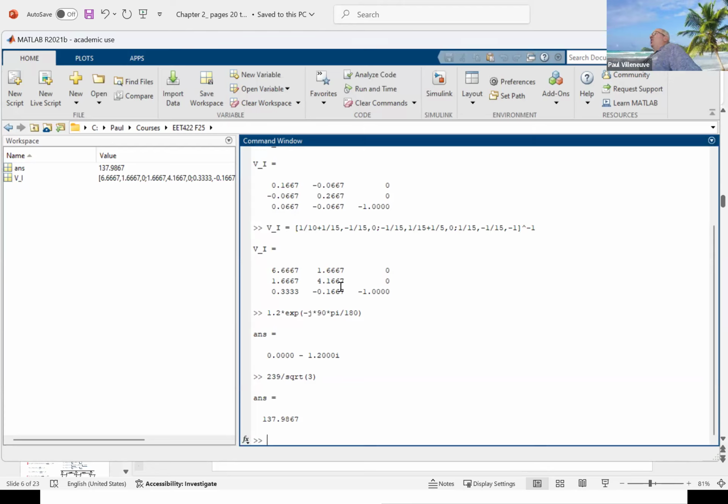Because now you're talking about a really long span. It's hard to get a tree that's going to be 100 feet tall that's perfectly straight. So when you've got to get really tall and you're running very long distances, you've got to run steel poles because the sag of the line will be so great that you just have to increase the height. It would be better to do it with wood poles if it's practical, but because you've got to get all over that roadway, you've got really long spans there. It's not practical.